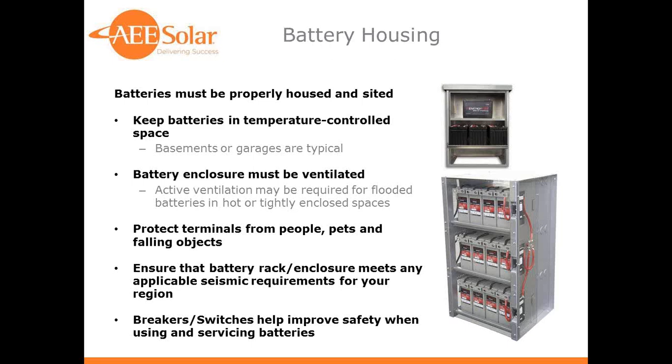But very often in situations with a lot of gassing with large battery banks, you do have to use active ventilation, essentially a battery vent fan. Zephyr is a company that we carry that provides those, to vent any gases out. These batteries we're showing here in the lower right are the Outback REE batteries, and they are sealed. Now, sealed batteries can still, on occasion, let out gases. So all batteries need to be vented, although it's extremely important for flooded batteries to have very good ventilation.